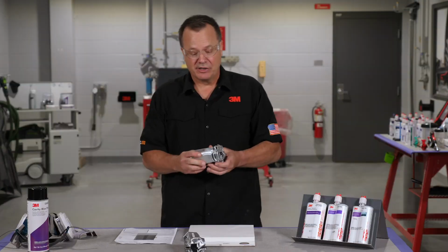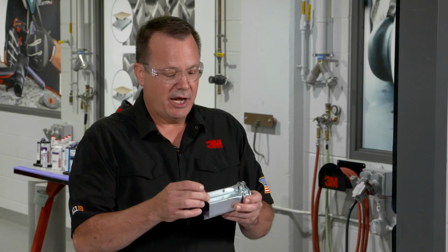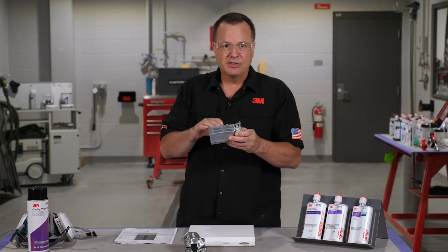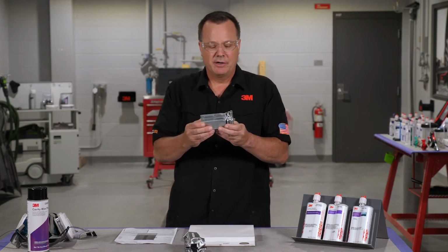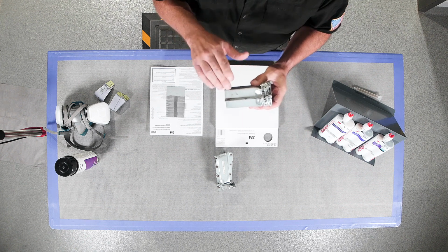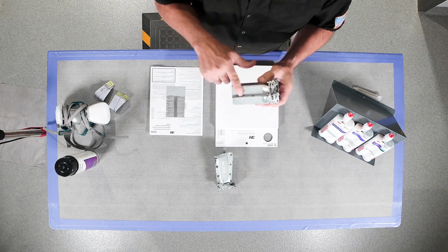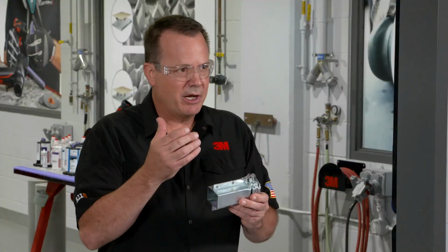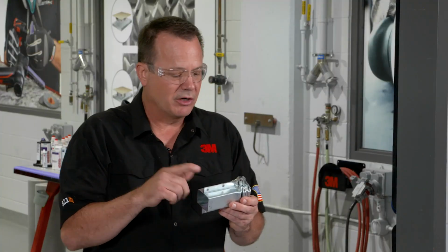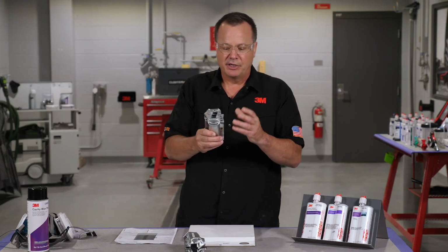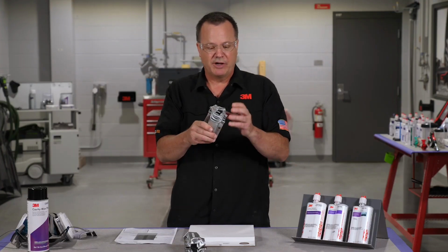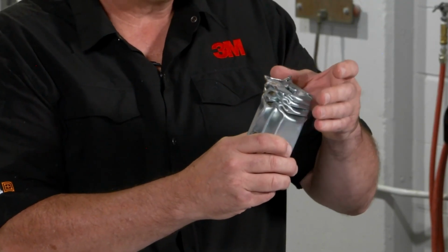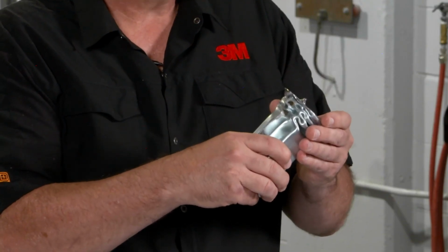So weld bonding is the combination of adhesives and welds in the joint. Why do we need both? Well, the adhesive adds a lot of benefits to that joint. One of the things is it prevents corrosion because you've got a completely sealed joint that you would not normally have with just welds. So it seals that joint to keep any moisture or air from passing through there and causing corrosion. Another reason is, in the case of the impact-resistant structural adhesive, it actually allows the part to collapse in more of a predictable manner and absorb energy as it collapses.